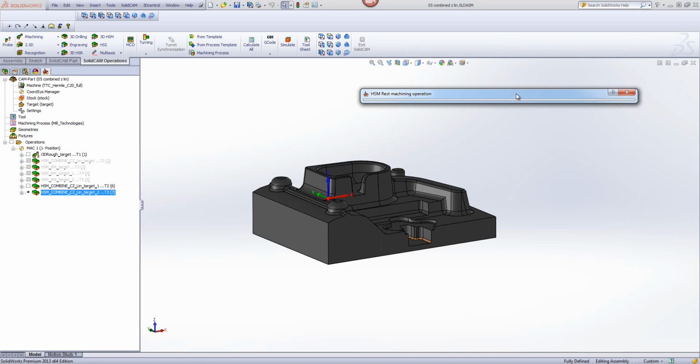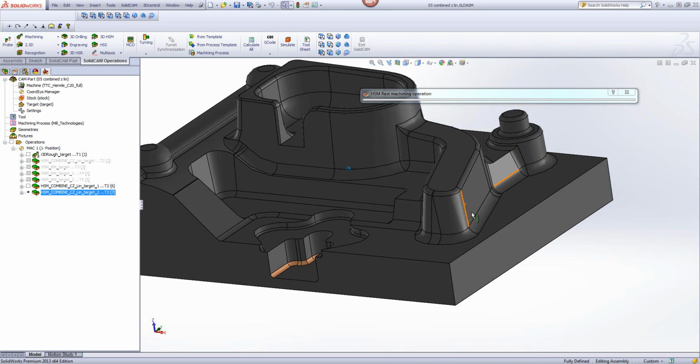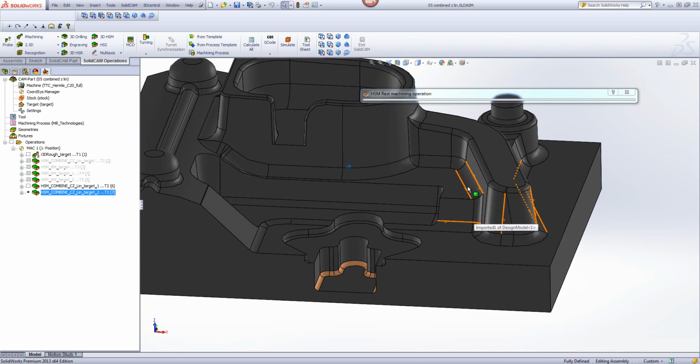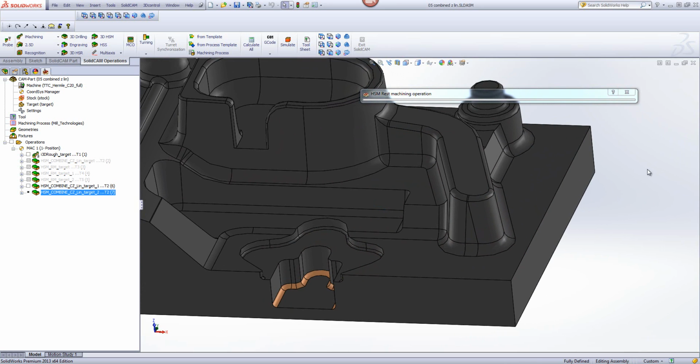Now, what exactly do I want to do over here? I want to clean away all the areas that were left on by the fillets. Now, over here I have larger fillets, and over here I have smaller fillets, as well as over here. Now, I don't want to work with my smallest end mill on everything, because that would, one, take a long time, and two, that small tool is taking off a lot of material, and I'll be lucky to have a tool left at the very end. So that's not the best way to work. So first I'm going to start off